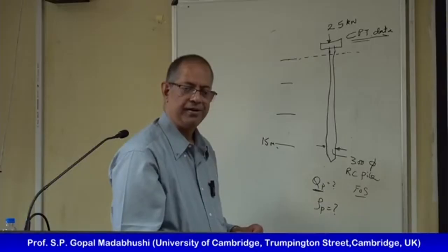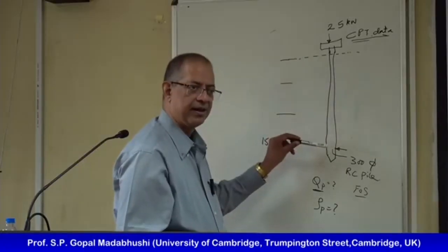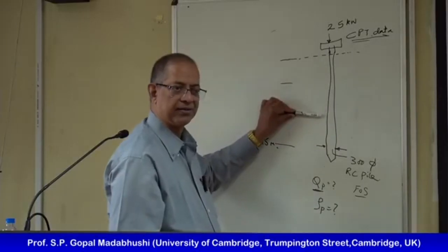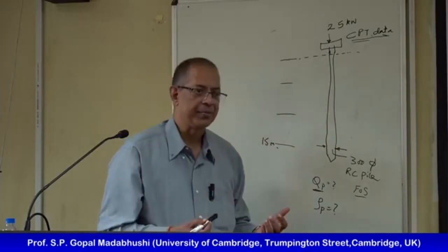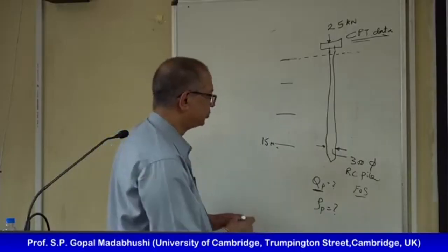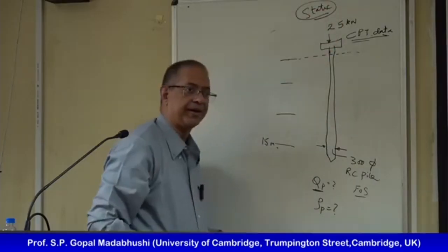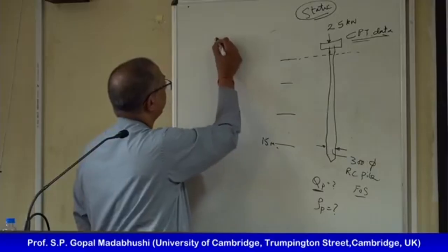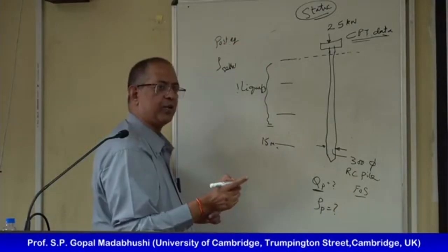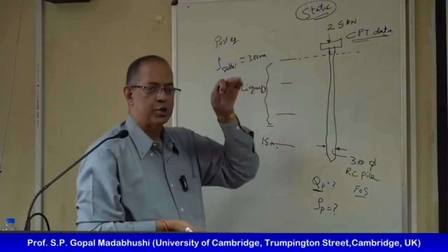Now, the other thing is, you also estimated for this problem that this soil will liquefy and settle, right? So what will happen then? This is all static, or pre-earthquake, but post earthquake, you got maybe about 300 millimeters of settlement of the soil layer.